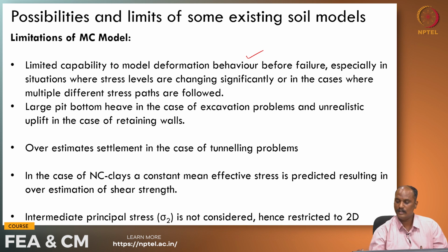Where multiple different stress paths are followed, this again is a problem. Especially when it comes to excavation problems or retaining walls, this particular Mohr-Coulomb model gives a large pit bottom heave. If this is a pit, you have this heaving problem, which is unacceptable, especially in the case of excavation problems.